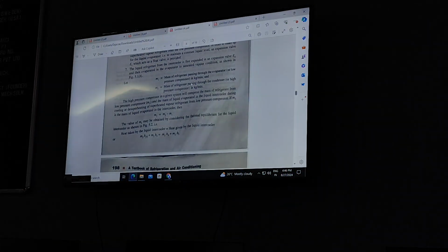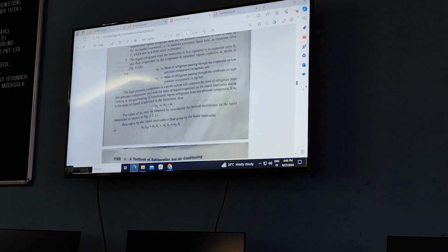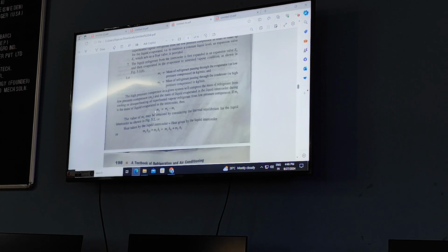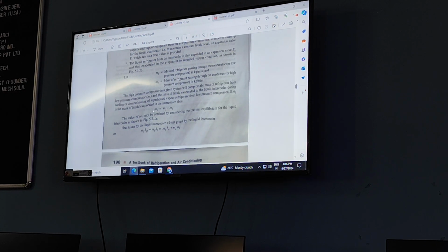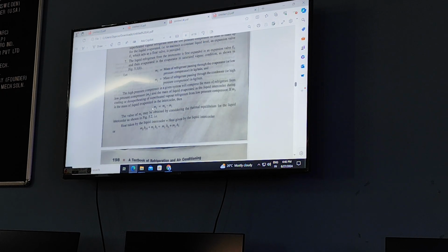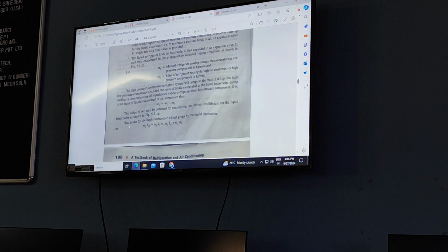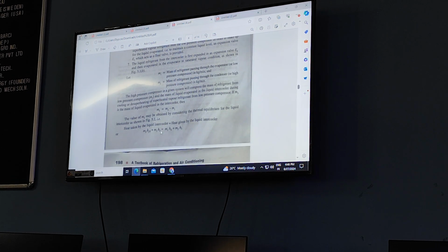Refrigerant circulated in the second compressor. M3 is what? Liquid refrigerant evaporated in the flash chamber because of the superheated vapor from compressor 1, and that is equal to M2 minus M1. Right? Now this M3 can be calculated by using the energy balance equation of the flash chamber.